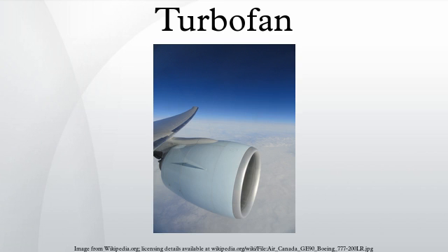Like reciprocating propeller engines, turboprops can be used with controllable pitch propellers, which allow thrust to be adjusted independently of the engine rotation speed. If the turboprop is better at moderate flight speeds and the turbojet is better at very high speeds, it might be imagined that at some speed range in the middle a mixture of the two is best. Such an engine is the turbofan.